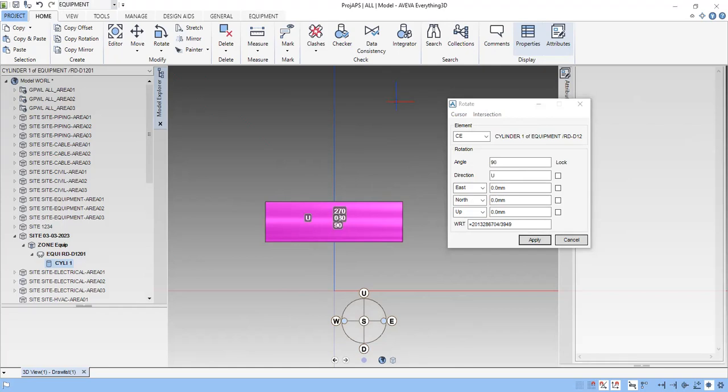When we work on a live project, at that time we should know the meaning of any command and when we have to use that command. So to save our time, if I want to rotate my equipment from the center, then why should I go to the design point? In an instant I can choose cursor element, just select my equipment and then rotate my equipment. Got it?